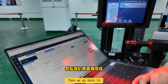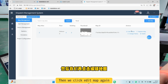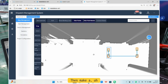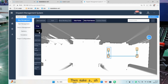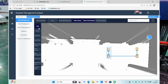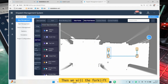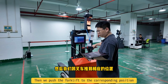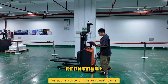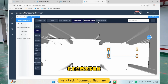Then we go back, then we click edit map again. Our 2 devices generally use one-way routes. Then make a one-way route dual channel. Let us click add route point. Then we push the forklift to the corresponding position. We add a route on the original basis. We click connect machine.